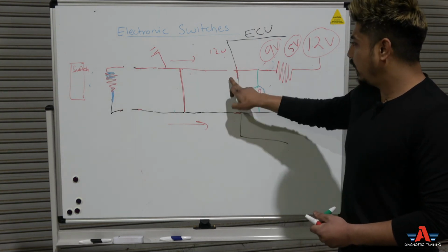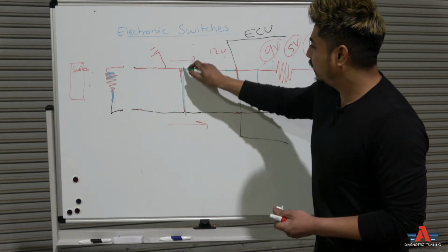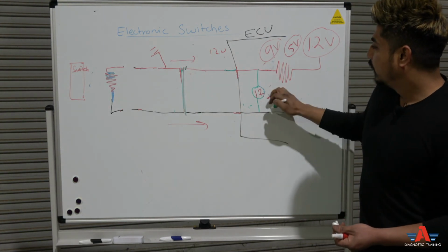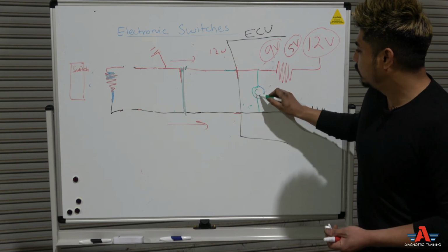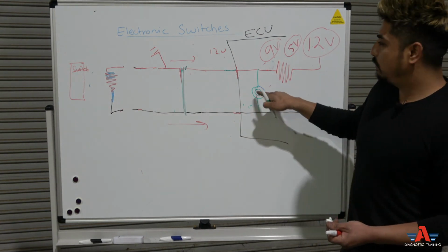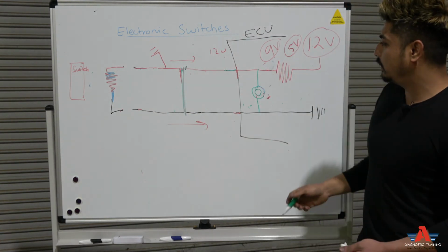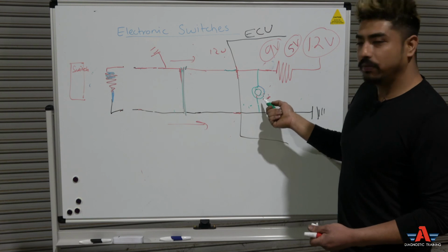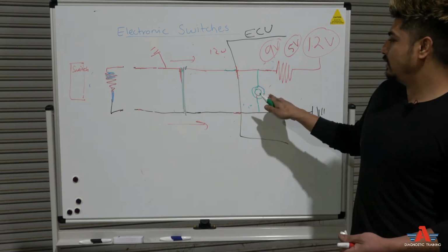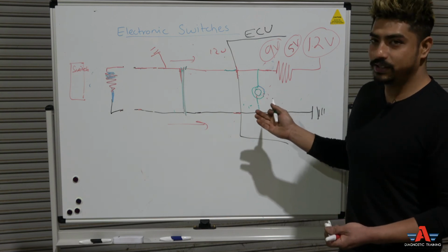If you disconnect that wire right here, let's say there's a short right in the wiring harness between two wires, whatever the case, or this is touching the body. You are seeing what here? 0 volt. Computer knows it's shorted to ground. You disconnect the sensor, this didn't change because the short is here, not in the switch, right? A coolant temperature sensor works exactly the same way. So you're going to see 0 volt here. Computer knows it's shorted to ground. You disconnect that sensor, nothing changed. Fault code didn't change, still sitting at 0 volt, right? Fault code description is still the same.